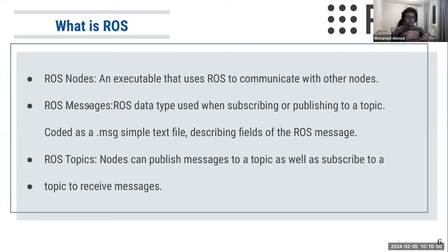ROS provides built-in messages. For example, for the LiDAR, it has a specific message, and for the camera, it has a specific message. And you need to parse this message in the correct way. Otherwise, you can't visualize your message, or you can't do anything with it. So you need to follow the rules of what the message structure looks like.